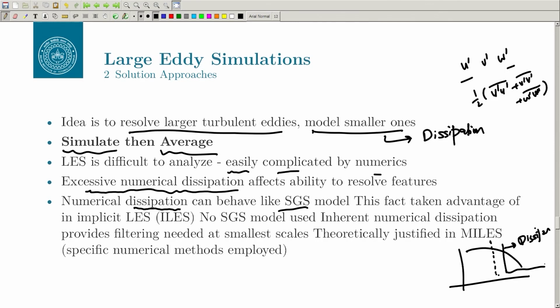the dissipation can take care of the dissipation of energy at the lower scales, which we are not resolving, right. So, the numerical viscosity can add to the natural viscosity, and it can give you the dissipation even at the higher scale, and that is why the simulation will go on, right. So, there are these two different schools, and without going into that, in the literature you will find all kinds of simulations in LES.